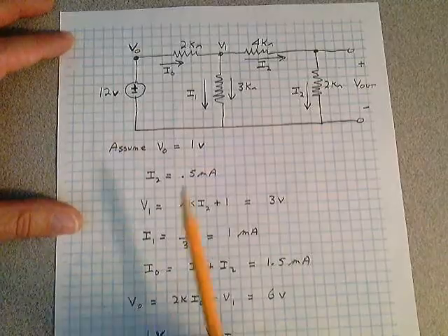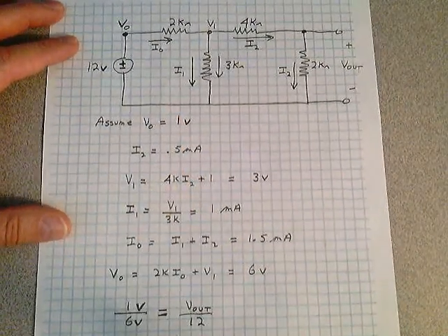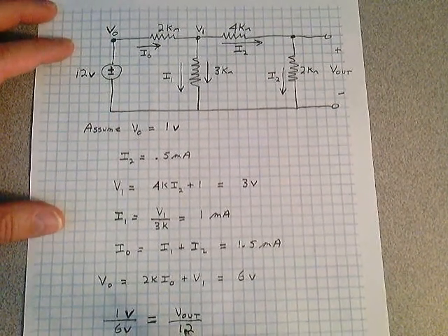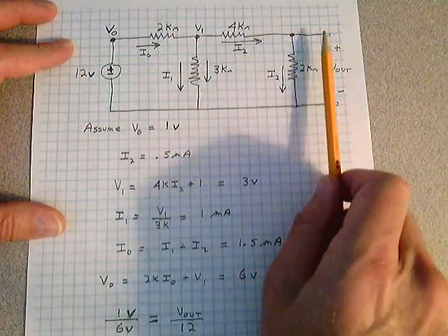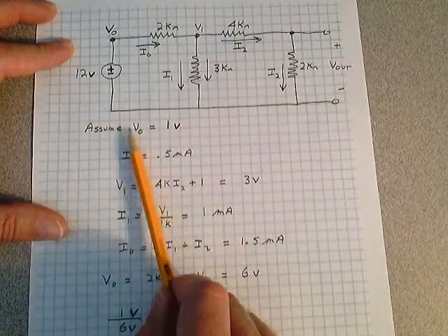But there's another way. We could use linearity. And you should be able to do this in your head. That's how this problem was intended, to just illustrate linearity in your head. We're going to assume, since we don't know what this output voltage is without going through an analysis like I previously discussed, that it's 1 volt.